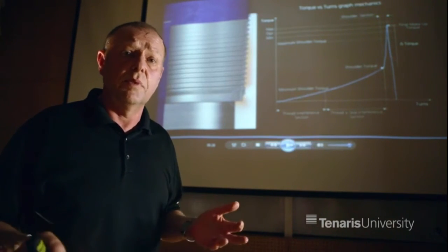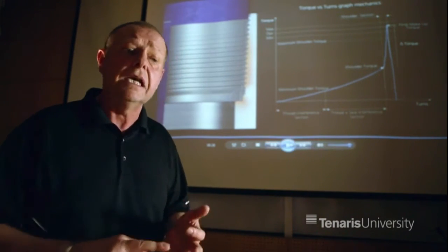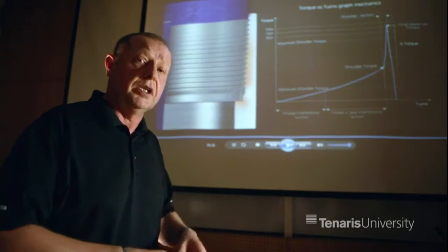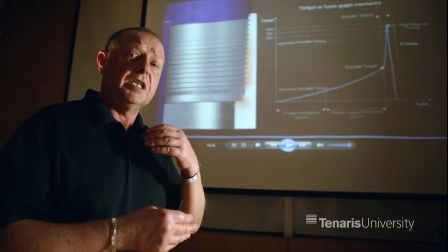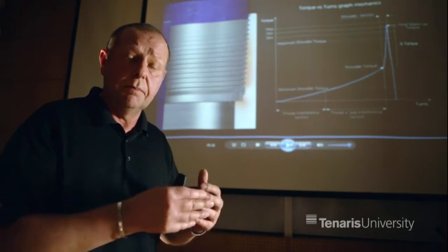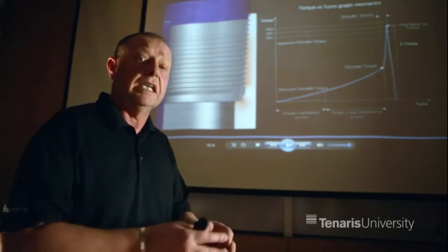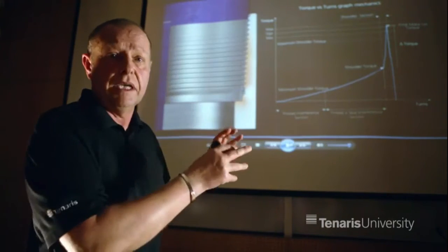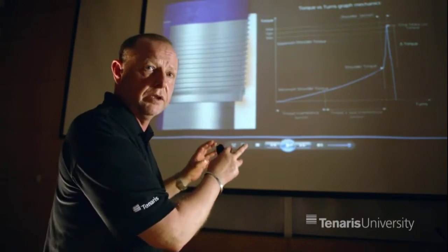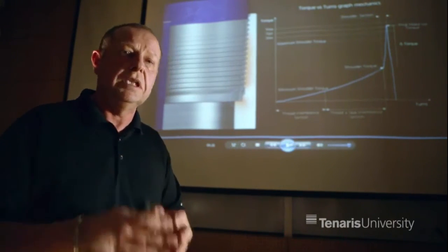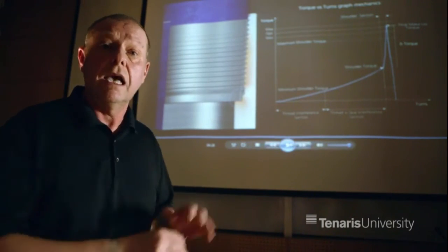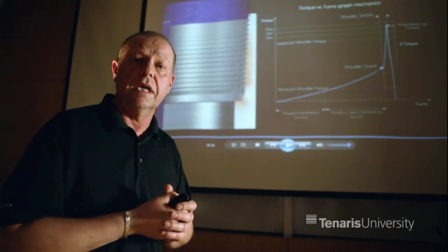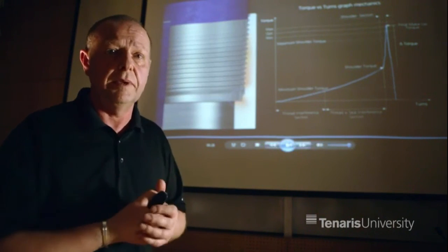This results in problems. It can result in an immediate leak, or it can result in that connection in service eventually creating a leak within itself, simply because the preload process, and that's what this is called, makeup is preloading the connection with energy, has not been completed as the manufacturer states it should. That's why you need a specialist to actually interpret these graphs. Not just anybody can do it.